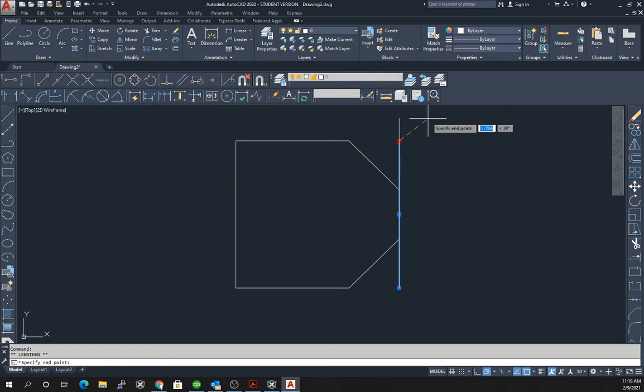So you sort of see this tracking line, but if you notice, the line only goes up. Even though I show a tracking line over here, if I click on this, all I did is make that a little bit longer. So lengthen does not change the angle of this line at all. It just makes it longer or shorter. So what we want to do here is lengthen. And I know this sounds wrong, but we want to essentially lengthen in the negative sense.